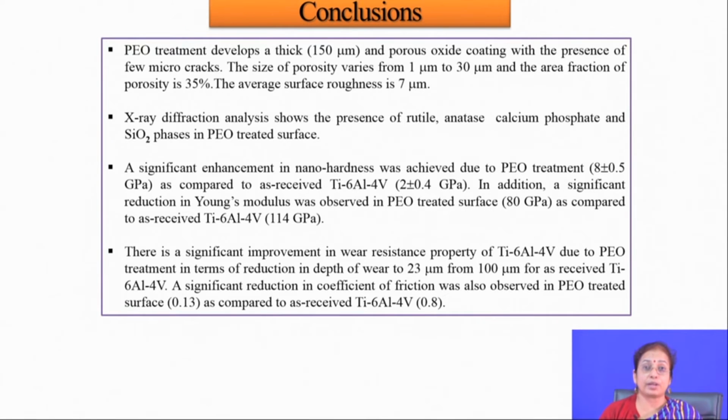And in fact, for any other chemical conversion coating also there is only a very thin oxide or very thin phosphate layer formed, because as soon as the surface is covered, the reaction stops. So, that is the limiting point. As soon as you dip it in solution, there is nucleation of that product, and then its growth, and it continues till the full surface is covered. As soon as the full surface is covered, everything stops.